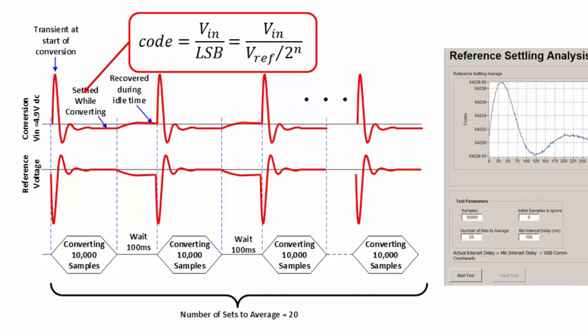A similar behavior will also happen in multiplex systems when transitioning between channels that are at significantly different voltage levels. In this case, the different conversion results from the 2 different channels will cause a significant shift in the ADC reference load current requirement. The shift in load applied to the reference will cause a reference voltage transient similar to the sleep mode case.